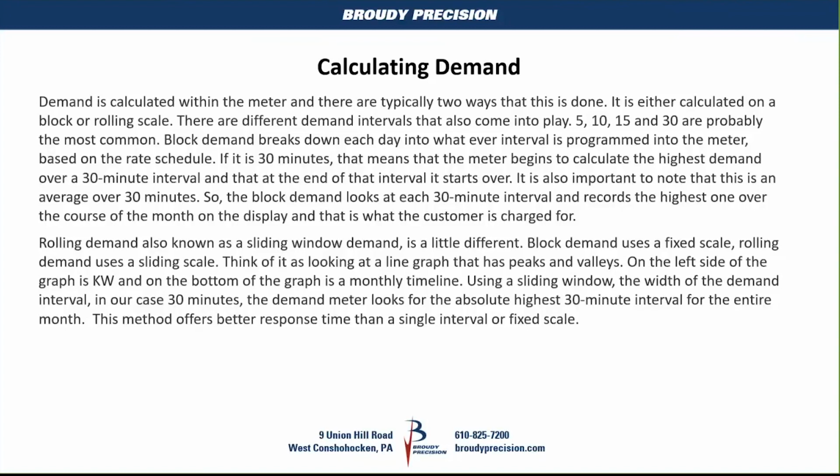So I've been talking about all this demand stuff, and the object here is to keep our highest demand, whatever that is, whether it's a 30-minute block or a rolling demand. The objective here is to keep that demand for the highest usage, instantaneous usage, as low as we possibly can. That's the whole object of this conversation.